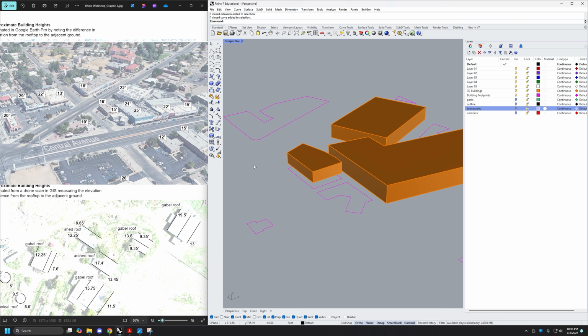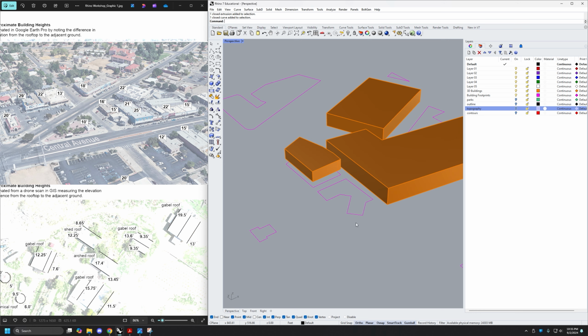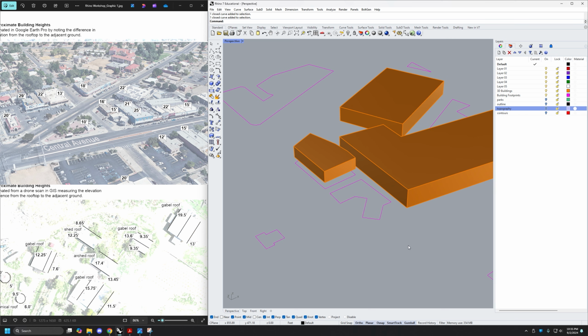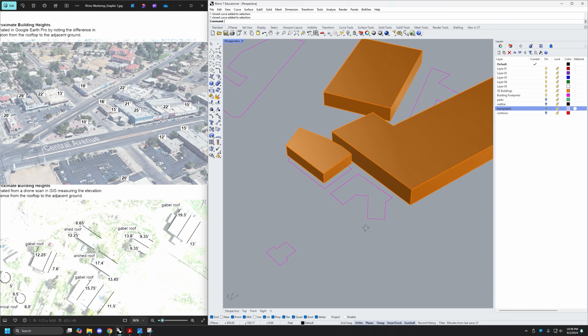Yeah, I think that's the most logical way to do this. So rather than extruding this one building, setting the height, and going back, I think part of this, and this is a good way of demoing this, is finding workflows that are grouped by process type. Doing all your extrudes at one point and then moving all your gumball things at another streamlines that production. So we don't want to be here all night.